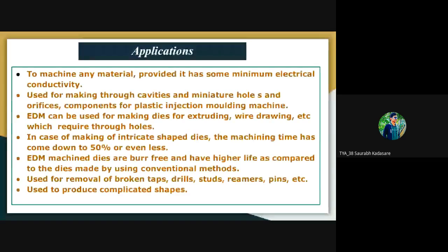That means sharp details were present now. So we can do EDM after heat treatment also, and it can choose better die material without worrying about it's a machining problem. Okay, again it can be used to produce shapes which are extremely difficult to make otherwise, which are squares or D-holes or splines or narrow slots and the grooves or blended features. So that type of different shapes are there now. So for that purpose also we can use EDM.